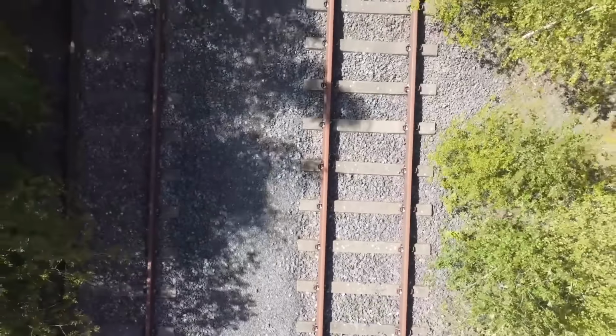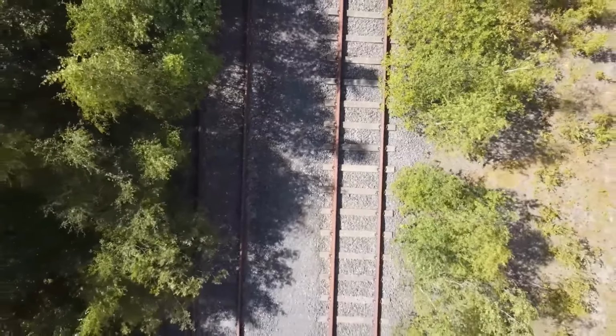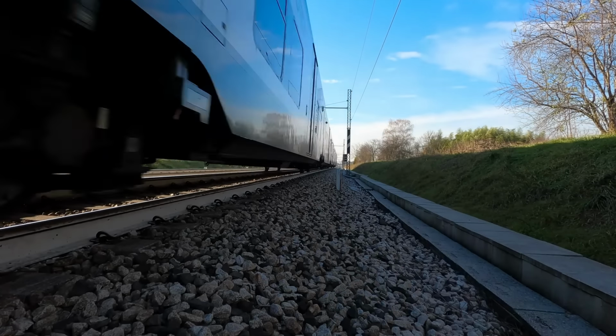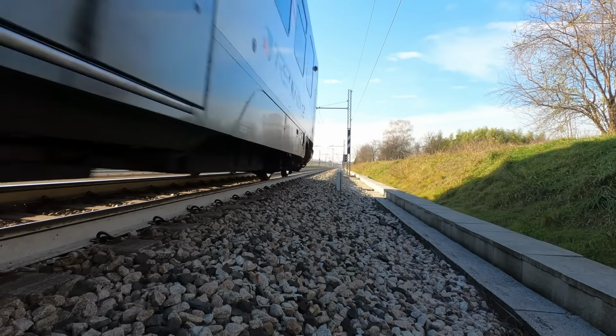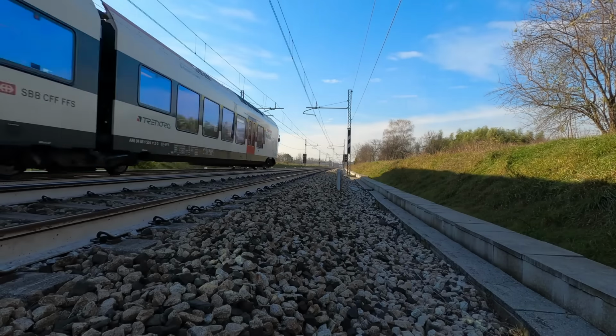You can see that there are a number of real-world factors that affect choosing an applied cant value when designing track. It is not straightforward, and draws on the knowledge of the designer or engineer. Knowledge of the operations in the area, as well as the balance of traffic, is key. It can be seen as a balancing act.